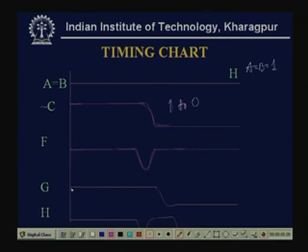See that G value is that during this transition again it will be some delay, and H again, where the F was there, that time some glitch will be. That means for this particular circuit, along with the static hazard, we are getting some more hazards.